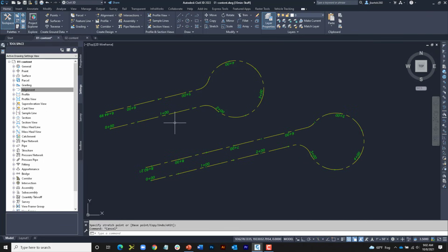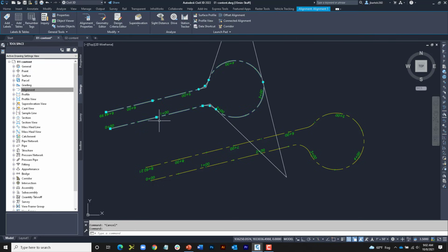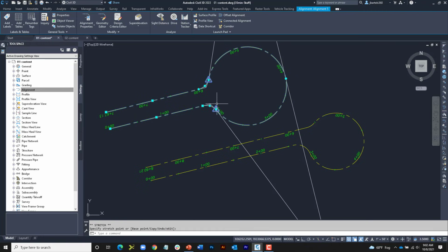Let me press escape. If, however, I select the same geometry that was created from objects, if I click the same grip here in the middle, drag this around, you can see that's not necessarily what I want. I've got no grip at the center. If I click this grip at the end, I could kind of pull this out and make the cul-de-sac head bigger, but it looks like it's a fixed object. It's not maintaining tangency. Let me click undo.